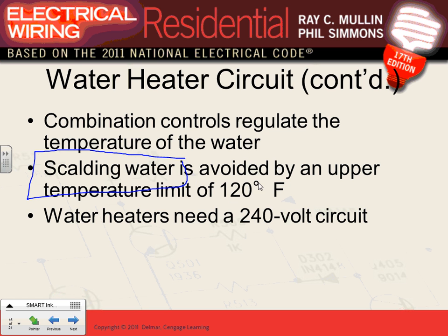Try to avoid reaching a temperature of 120. There's a lot of control issues, guys, in it, so it doesn't give you very hot water. It shuts down. There's a lot of safety issues. If the water gets so hot, it shuts down. There are valves that open if it turns into steam, and the worst thing that could happen is you change water into steam. You basically created a steam bomb. Everybody knows that? And fast, bam, explosion.